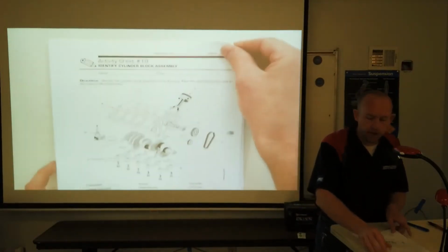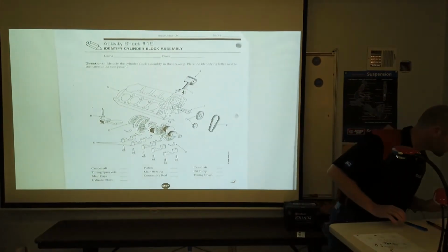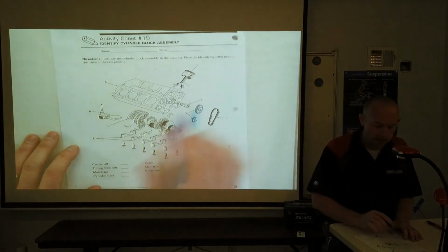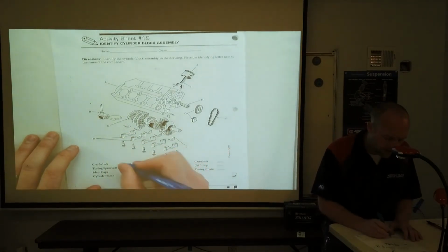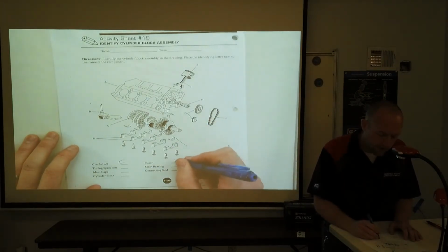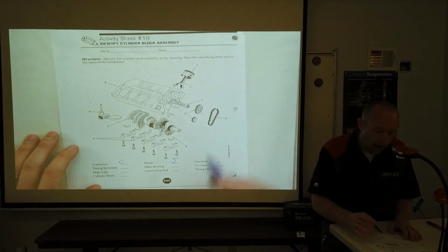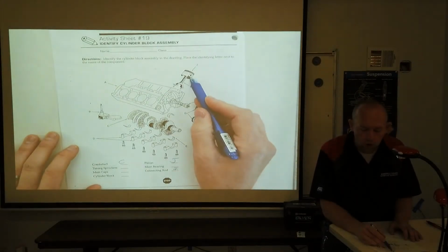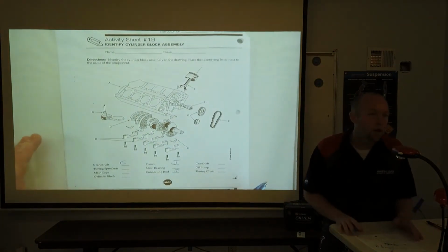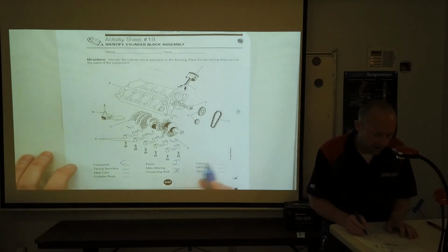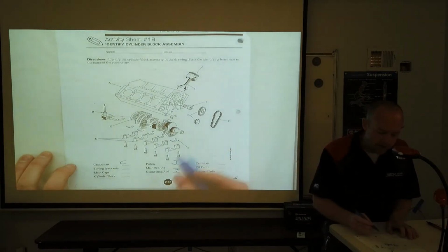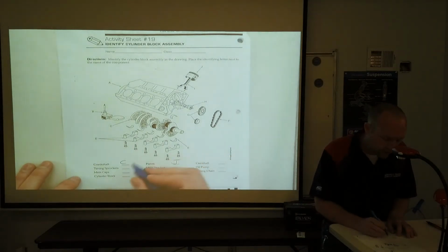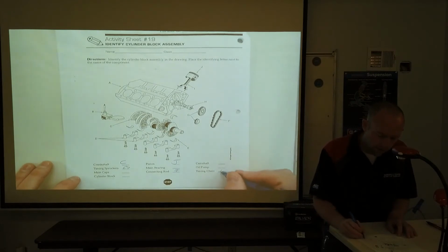So then looking at our bottom end components here, the crankshaft, which we connect our pistons and connecting rods to, would be C. Then the piston itself is J. Then if I move down to our connecting rod, typically the little hole that's right there on the piston would be called the wrist pin, and that's what pins the connecting rod to the piston head. Then our timing sprockets, which allow our chain to connect our cam to our crank, would be G. Then the timing chain, F.